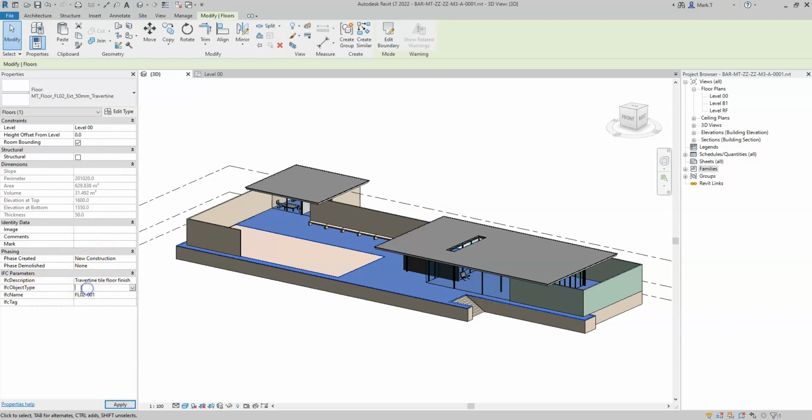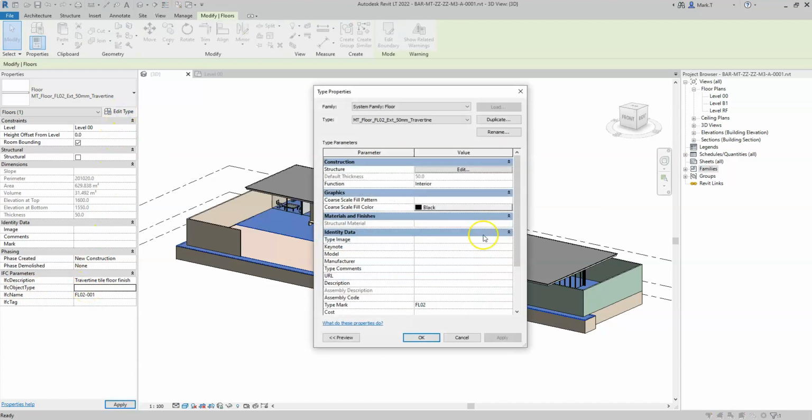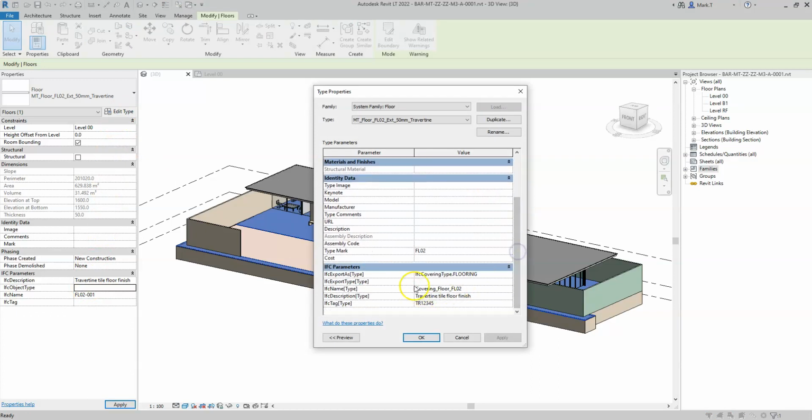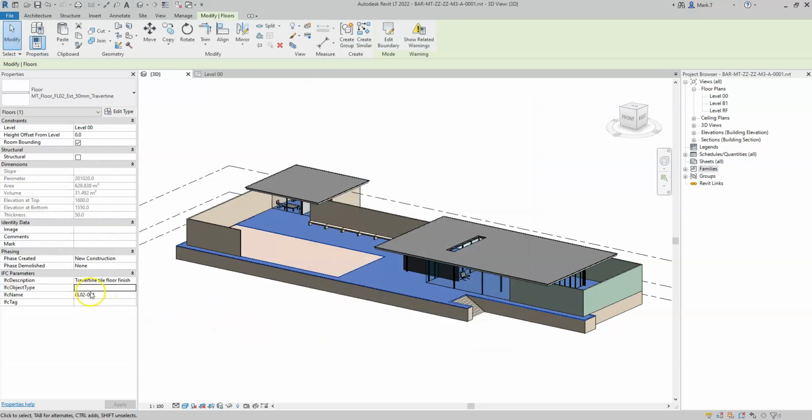The object type is a tricky one because this is usually only defined at the occurrence level when the predefined type of the element is set to user defined. This was okay for IFC 2x3 when there were not many predefined types for particular entities. However, it's unclear what this should be filled in with by default.